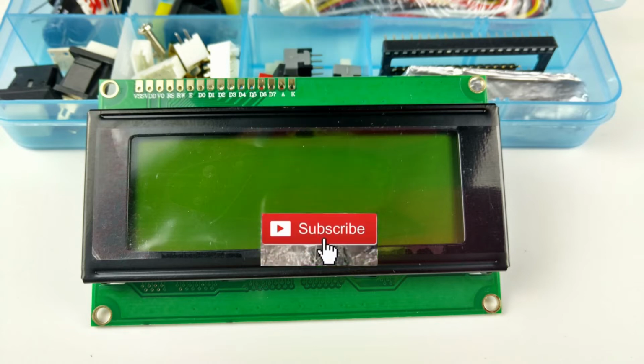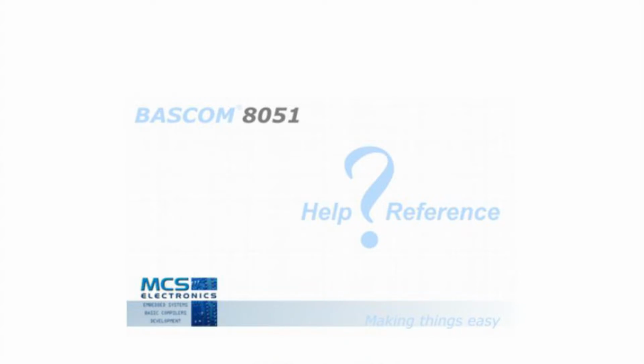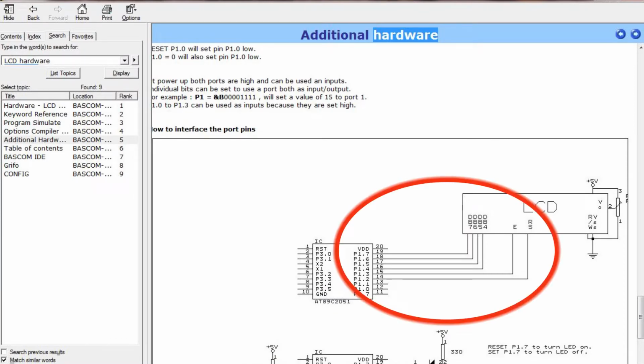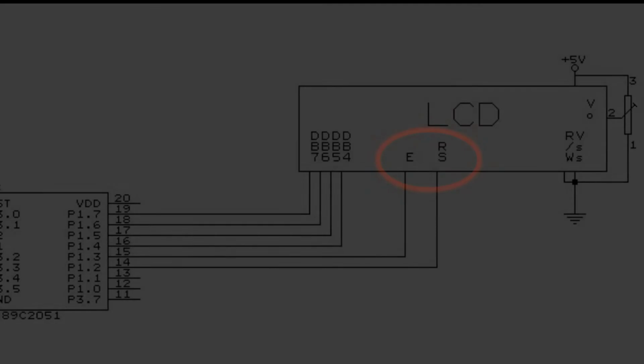So how did I interface this 20 by 4 LCD to the micro? My source of information is the BASCOM 8051 reference manual, which recommends the LCD hardware interface on page 228. Take a look at that. The way it is connected to the micro is in the 4-bit mode, wherein there is a 4-bit data bus, DB7 to DB4, and there are 2 control lines, the enable and register select, or RS.